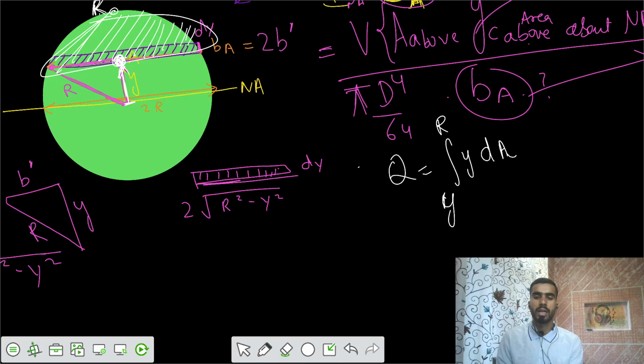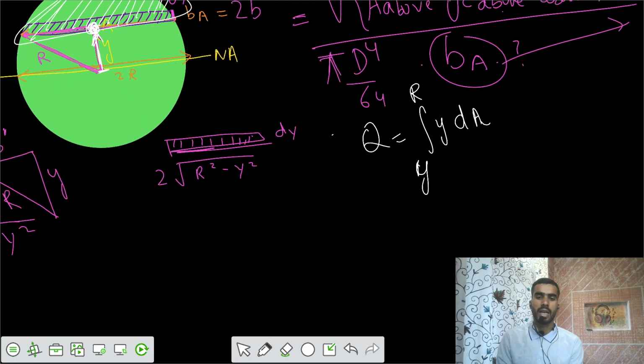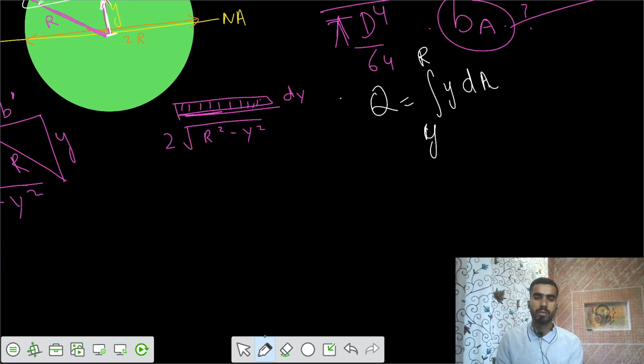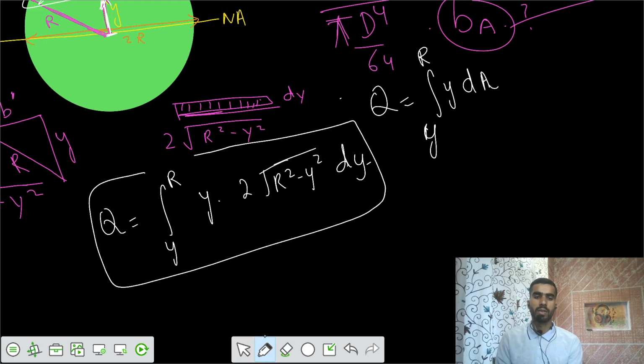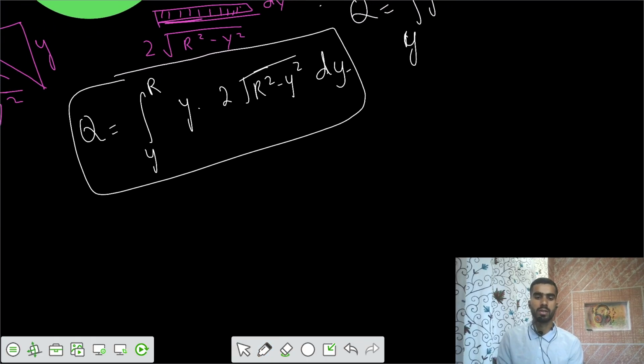So you have to integrate it, and we have a small differential area also. This is your differential area. That means your Q value equals integral from y to r of y times dA. The value of dA equals 2 times root of r square minus y square times dy. So we got this first moment of area, and you need to solve this one. How can you solve this? y into 2 root...